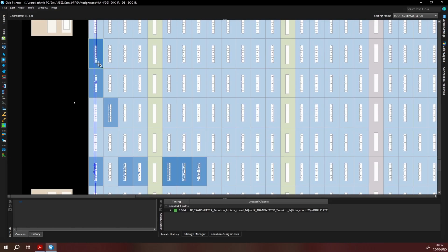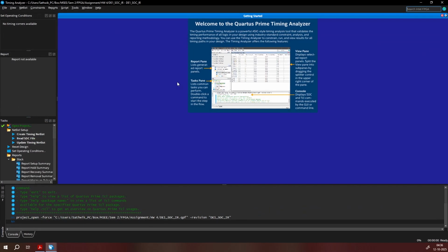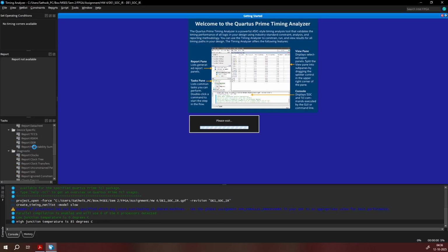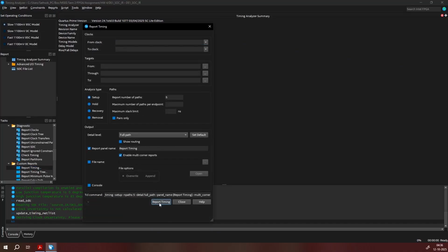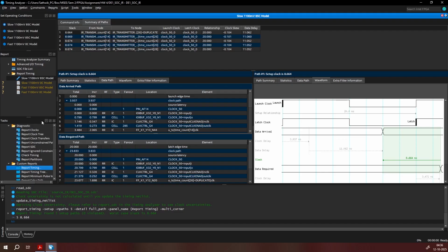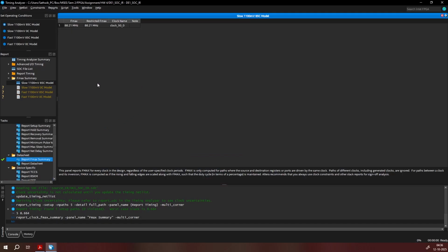So this is the modification that we have done on the physical design, and the results can be seen on the timing analyzer, where the slack has reduced close to half and even our Fmax has dropped by 50%. So yeah, those are the main things that we can see by modifying the clock period or by modifying the placement of the resources on the chip.